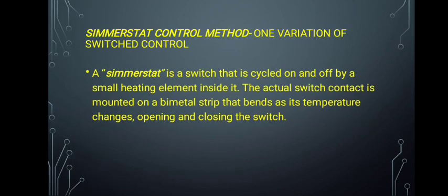Simmerstat control method, one variation of switch control. A simmerstat is a switch that is cycled on and off by a small heating element inside it. The actual switch contact is mounted on a bimetal strip that bends as its temperature changes, opening and closing the switch.